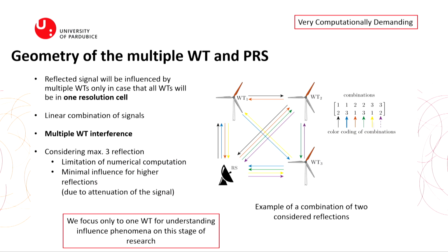And what will be the result? The result will be that in the spectrum or spectrogram in time there will be all Doppler shifts, because you make a summation. It is one reflection surface, but each element rotates with a different speed, plus pulse transmission, plus rotation of the radar, and all you need to compute well, and the result will be one signal.